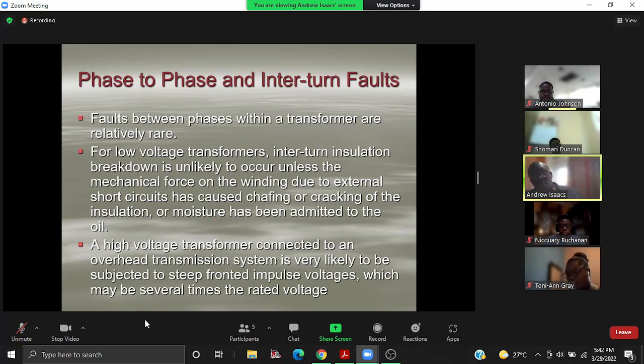Yes, sir. Now, what we did not speak about was the characteristic of the waves. So you'd have a similar waveform, all right, for a switching as well as a lightning pulse. However, the difference between the two would be in terms of the rise and fall. So one is a lot sharper, one is a little more gradual. All right.